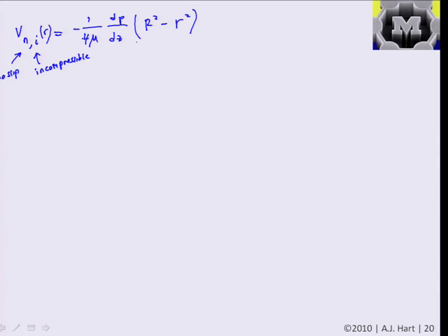And then if we wanted to find the flow rate, we can give it the symbol Q, which is typically used for flow rate. And the flow rate is just the integral of the velocity over the area. So we can just take the integral over the area of v of r times our differential area dA, and the dA of a circle is just 2 pi r dr, because we can integrate the thetas right away. So this would be just equal to 2 pi times the integral from 0 to R to capture our velocity distribution in the r direction times r v of r dr.